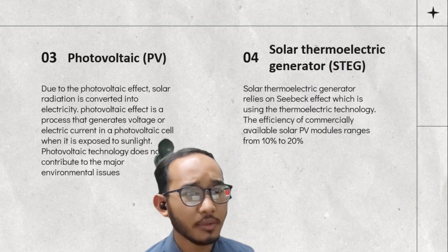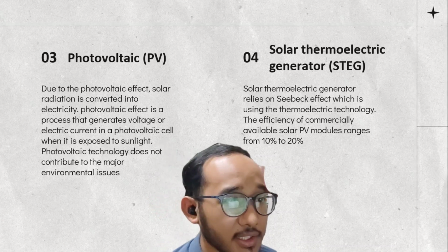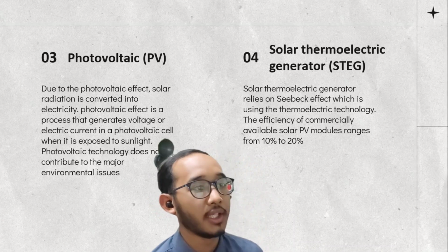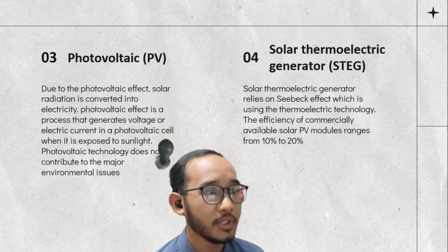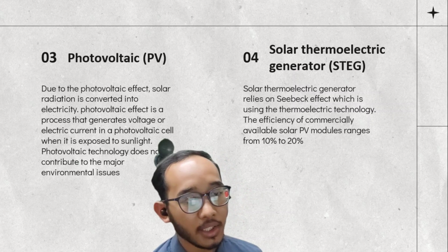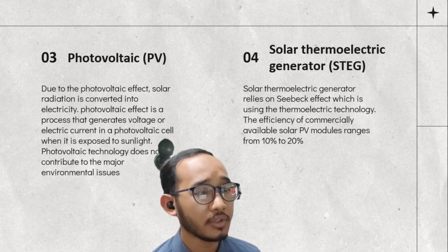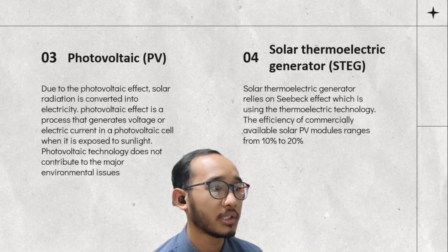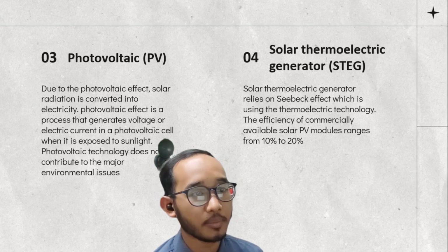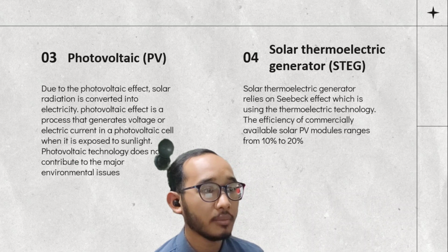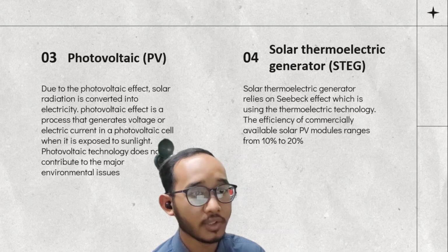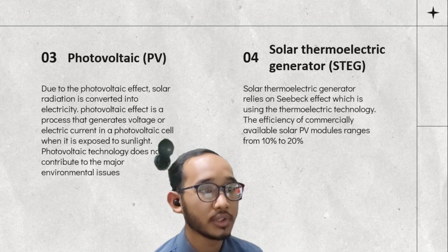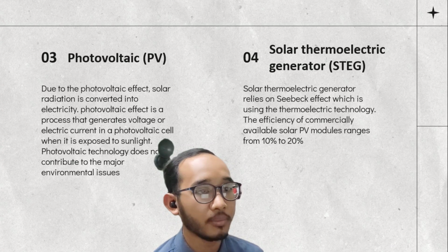So for STEG, when compared to other solar technologies, STEGs have a number of benefits that make them superior. STEGs are solid-state devices as opposed to the classic solar thermal generators, which means they do not have any moving parts, which significantly boosts their dependability and durability. In addition, STEGs are a scalable technology that may be applied on either a small or a large scale, depending on the requirements of the application. STEGs employ a wider amount of the solar spectrum in comparison to photovoltaics, which are restricted to only using the portion of incident solar radiation that is above the band gap.